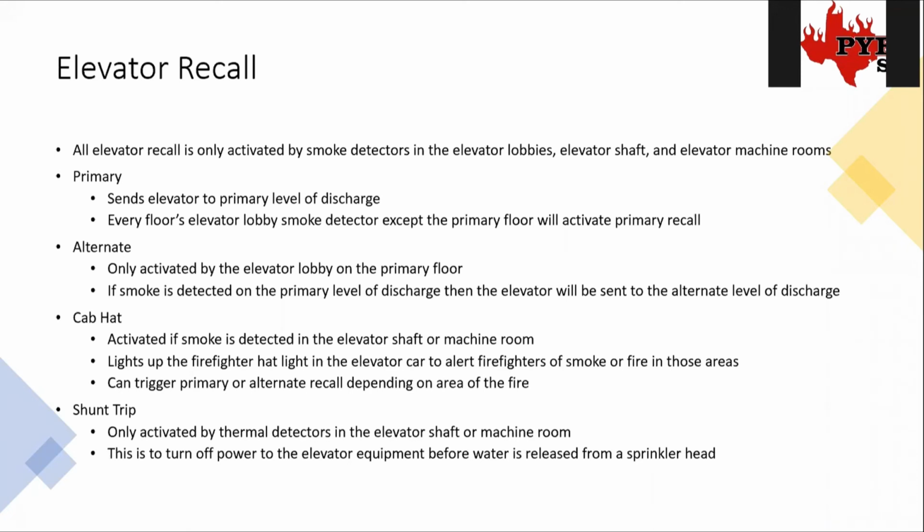Outside of the City of Houston, all the elevator inspectors, all the fire marshals, they all want it to shunt trip immediately. But inside the city, they want that delay to happen so it goes to wherever it is and then opens. Most of the time, a 30-second delay works great for it, so you just set it to 30 seconds and don't worry about it.